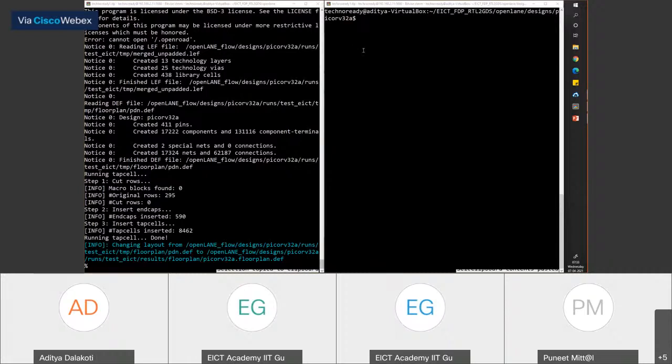Okay, how do we know the exact pin numbers to define for industry design? Pins are actually decided by the RTL designer, right? You do not design the pins from the implementation flow perspective. Pins are whatever the IOs are for whichever design hierarchy you are working on. If you're working at the top level, then they connect directly to pads. And if you're working in a sub block, then whatever the RTL designer gave you, those are your pins.